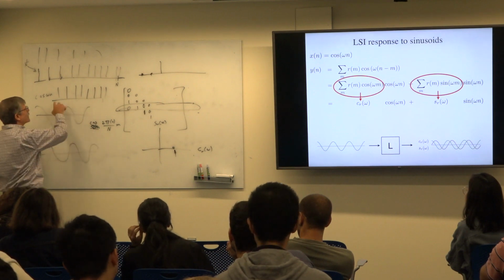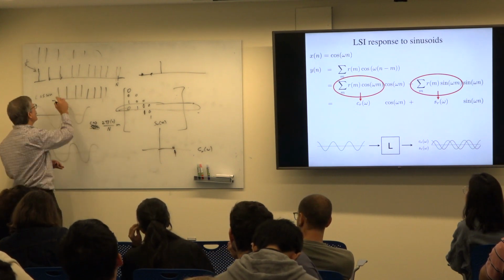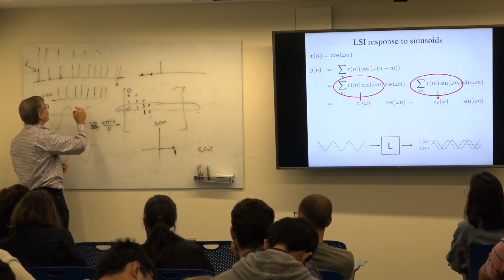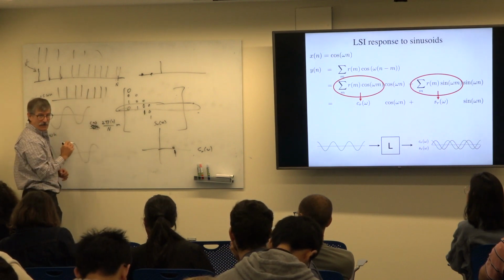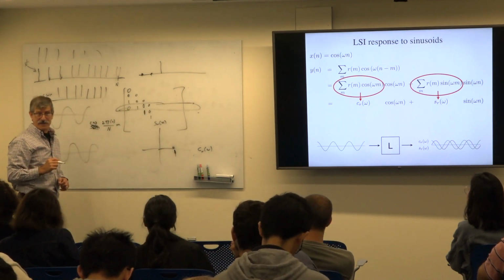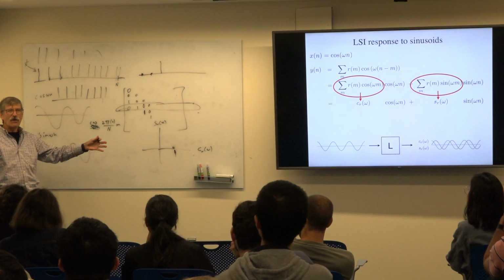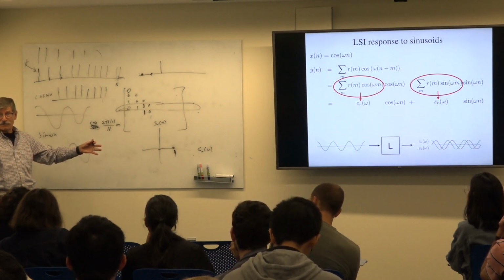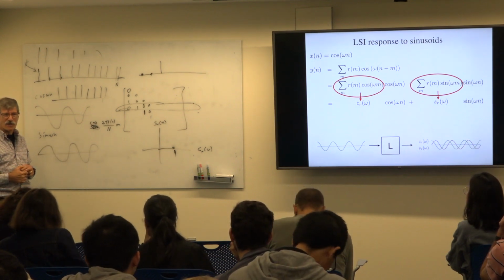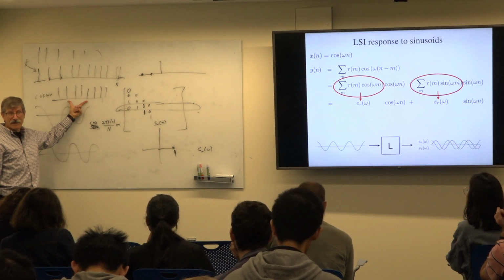I'm not actually doing the math, but you can imagine if I have like 8 of these, somebody goes up, down, up, down, up, down, up, down, cancels, dotted with this. Somebody who goes up, down, down, that's half the frequency, cancels. Somebody who goes up, down, cancels. But somebody who goes up for 8 and goes down for the next 8 and up for the next 8 and down for the next 8 doesn't cancel. So what I'm saying is, if you average the input for a long period of time, then you're blurring the hell out of it, and so high frequencies get quashed. Okay? So that's a bit of an example to think about intuitively this math. Which frequencies get through, which don't, or which frequencies dotted with this, correlated with this, give you big numbers, they get through. And if they give you small numbers, they don't.